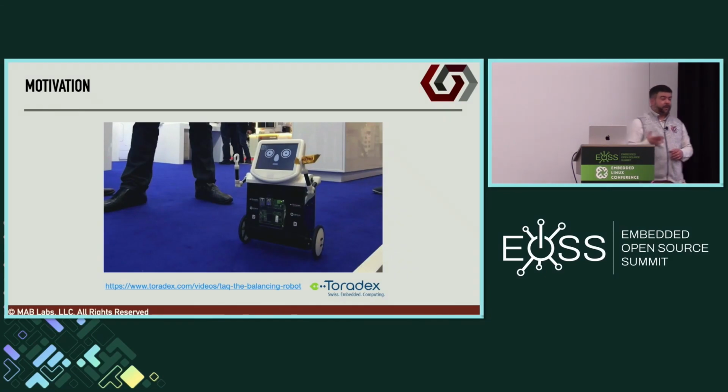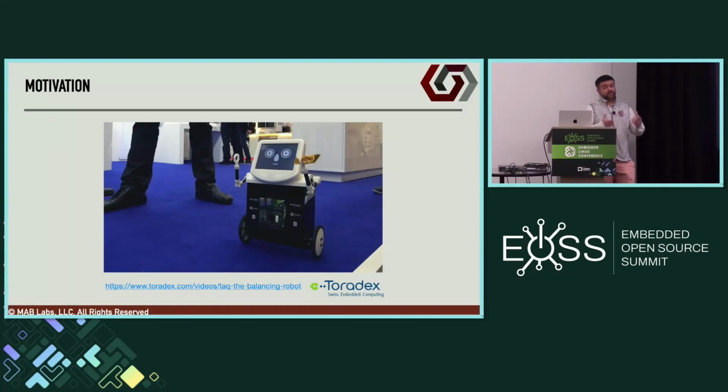So for example, if you were at Embedded World last week, you saw this robot from Cortex, and that had an IMX8M+ SoC from NXP, and then you had the MCU responsible for the motor control and the actuation on the robot itself, and then the Cortex A ARM device that's on the same silicon was responsible for the GUI, the interaction, and any sort of communication. So it's an example of what sorts of capabilities you have on this. It's a pretty small device, which is pretty cool, right? As you can see, somebody's leg is right there. So it's self-contained, it's pretty low power, and physically small.